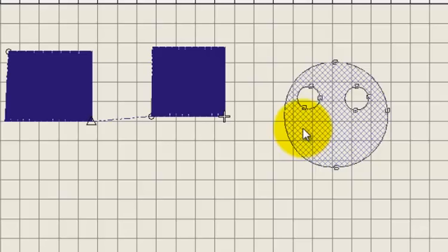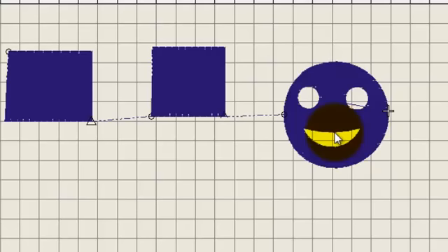Now I'm going to put a smile on them, so a left click for a curve, a right click for the bottom of the curve, a left click for a hard sharp angle, a right click for the bottom of the mouth, a left click at the other side, a right click, and then we just hit enter. Now I've finished creating holes or shapes, so hit enter once again. It's going to come up with some suggested angles. I'll just accept those, hit enter once again, and there we have it.